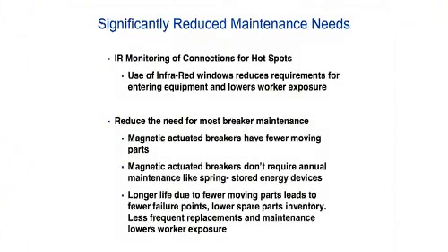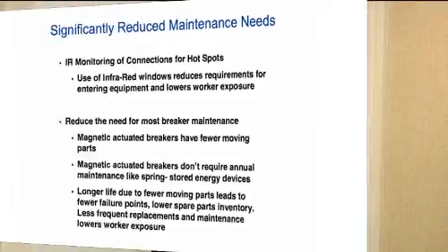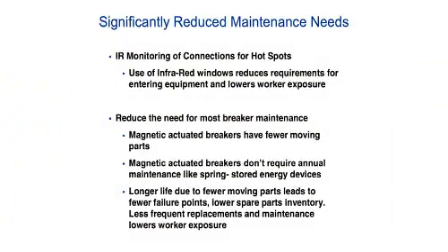The next item is IR ports. And why do I put that up here as a mitigation? Because if you recall my discussion about the 90% failure of stress cones, this is why. Because if you have an IR port and you're thermally looking at this switchgear on a regular basis, first of all, you're not opening up doors, which is the number one thing.